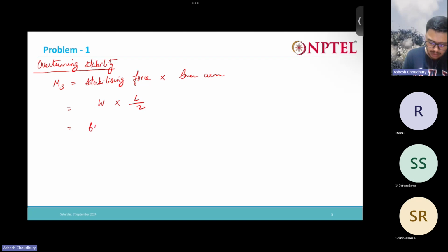Did you already calculate? Okay, this is the stabilizing moment. Now what is the disturbing moment? The disturbing moment is coming from what? From the earth pressure, lateral earth pressure. That is the disturbing moment. So P1 times h by 3 plus P2 times h by 2.